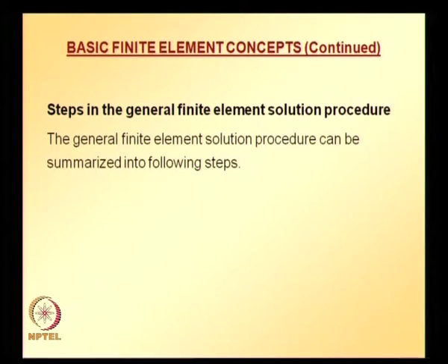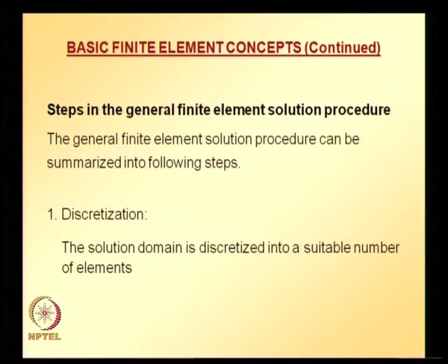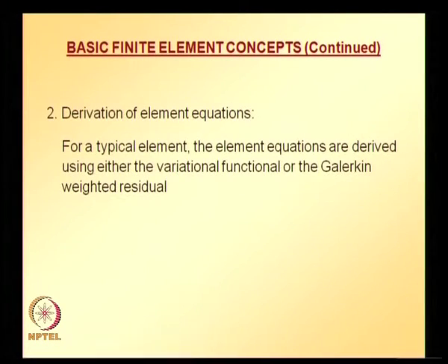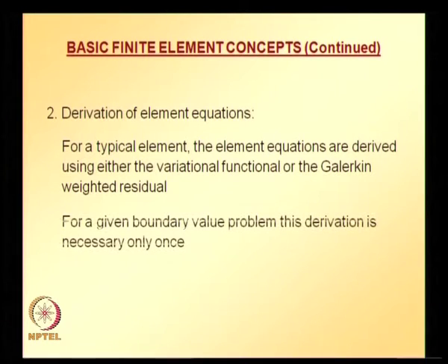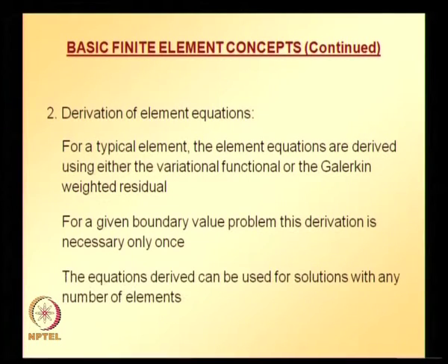So, the first step is discretization. The solution domain is discretized into a suitable number of elements, and derivation of element equations. We will do it for a typical element. Element equations are derived again using either variational functional or Galerkin weighted residual. For a given boundary value problem, this derivation is necessary only once, because you will see in a while, if you do it for a typical element, that is enough. The solution derived can be used for solution with any number of elements,